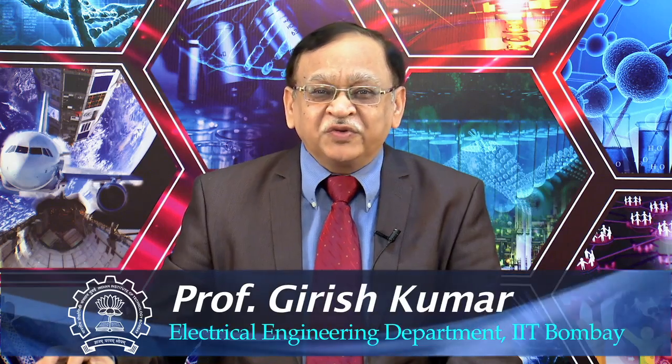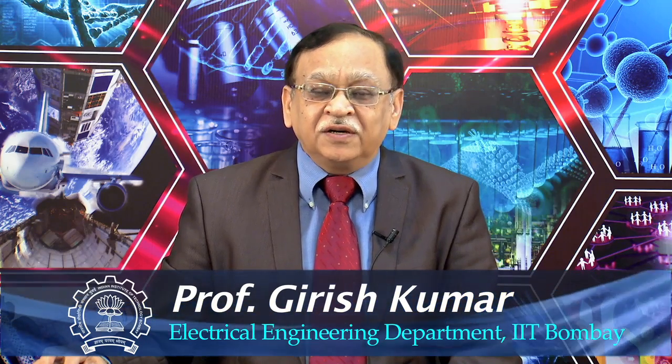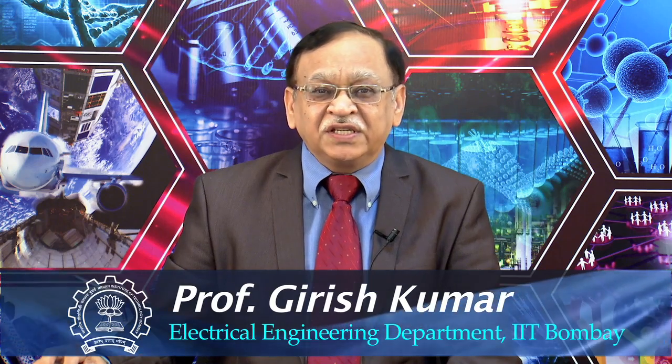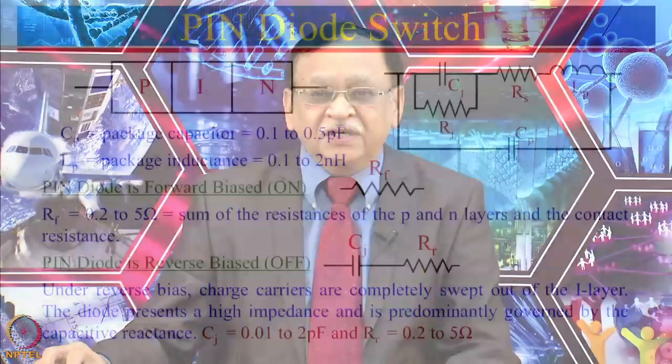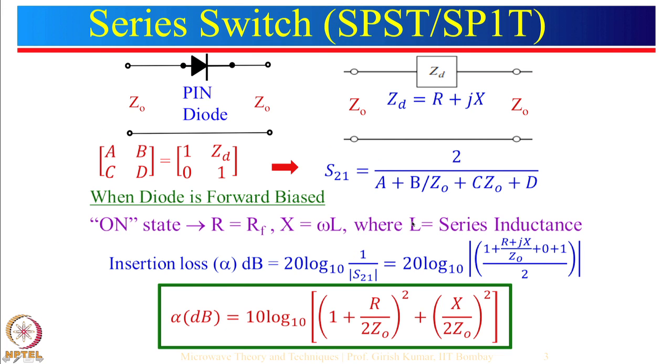Hello everyone. In the last lecture we had talked about RF switches, and our main discussion was on the single pole single throw switches, which had been realized using PIN diodes. We looked into the circuit configuration of the PIN diode. When the PIN diode is forward biased, it can be represented by a series resistance and a series inductance. When it is reverse biased, it was modeled as Cj in series with resistance Rr. Then we had discussed several configurations of SPST.